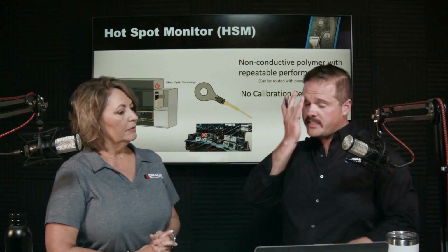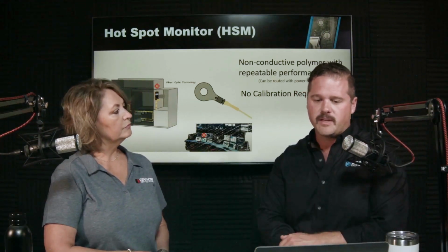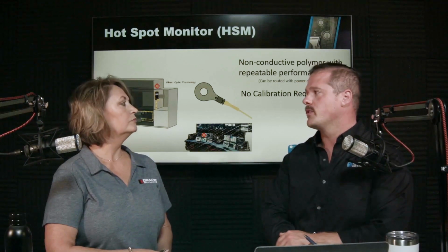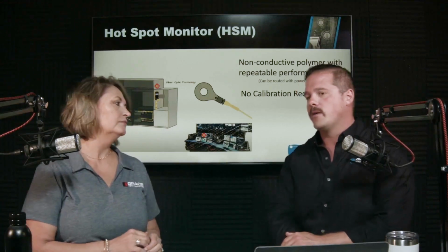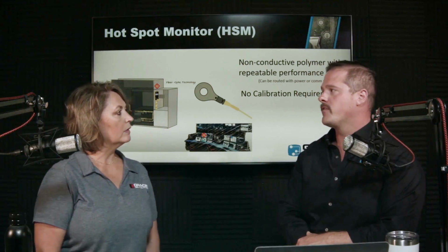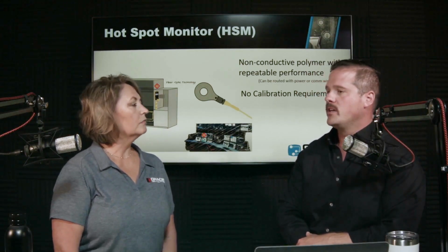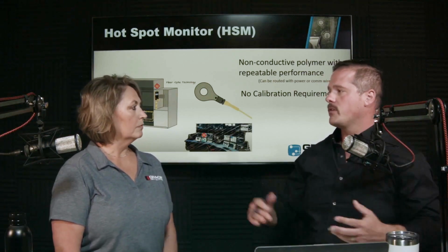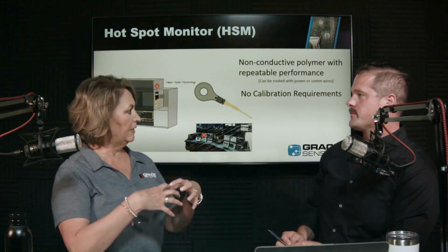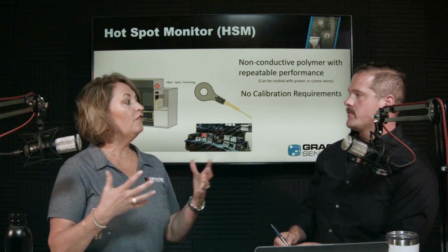Just going back to that 70B standard while we're on the interval, someone here said that their standard has been once a year, right? But duty cycles are also incredibly important, correct? Correct. And so if your standard has been a year, but the makeup of your facility has changed and how frequently things are duty cycling has changed, that would also alter potentially how frequently you have to do maintenance. Yeah, your predictive techniques are now contributing to your electrical maintenance plan. All of it is a plan, and it's an evolving plan.